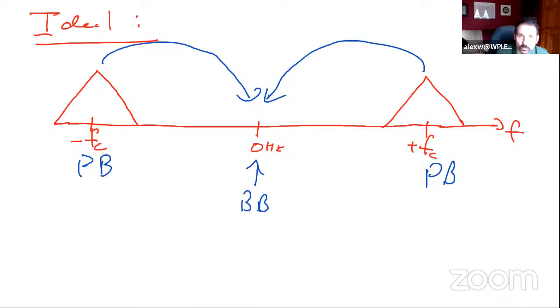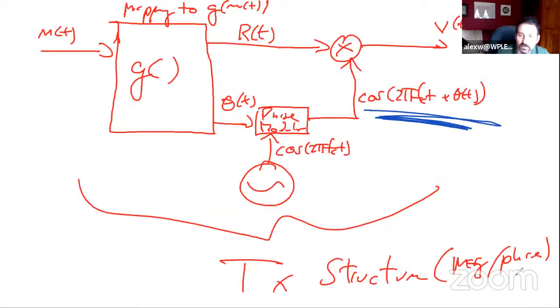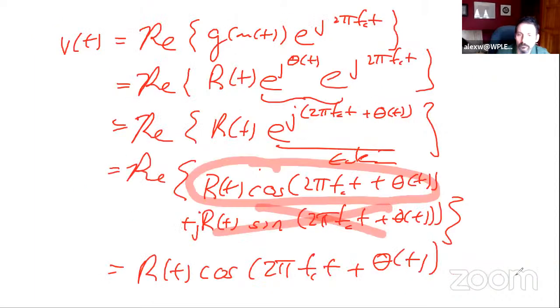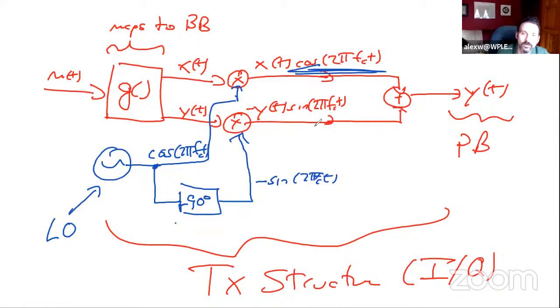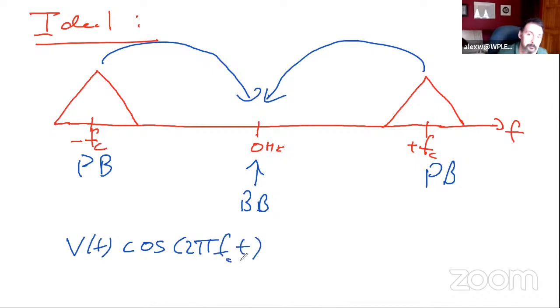So what you do is you demodulate. How do you demodulate? Well, we modulate using a cosine. Same thing here, cosine, and if we're 90 degrees out of phase, sine. I want to take whatever my passband signal is, let's say that's V of t, and to demodulate, I would need to multiply by a cosine with the exact same frequency.